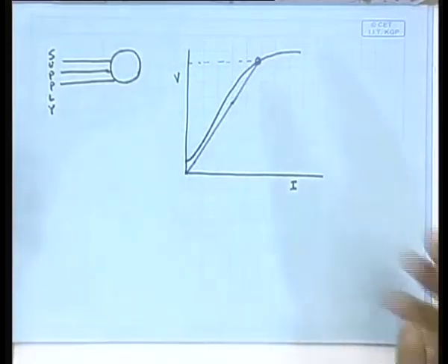If you actually do this on an induction machine, you will find that there is a capacitor connected across the induction machine, and you have by some external means rotated it. In your laboratory, we do this experiment with a DC machine being run as a motor to mimic the behavior of the wind turbine, and in that case, as the speed of the drive increases, you will find beyond a certain speed, suddenly the voltage will shoot up to this point. Okay. What is the point of this beyond this certain speed?